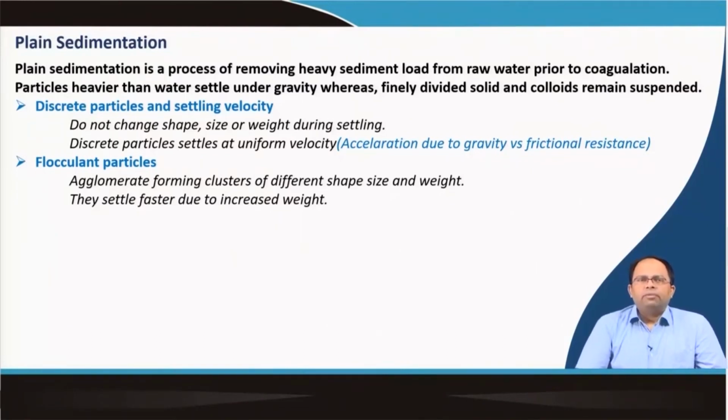Next, from aeration we go to plain sedimentation, and plain sedimentation is the process of removing heavy sediment load from raw water prior to coagulation, and particles heavier than water settle under gravity, whereas finely divided solids and colloids remain suspended. And as we have learnt already, for those kinds of colloids we use coagulants which are mixed into the water, and we can mix it through flocculation, and then these form coagulants, and gradually due to sedimentation they will come down, and clarifiers could be used to remove those sediments, right.